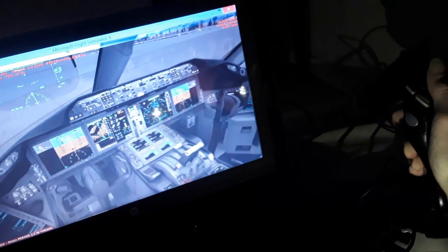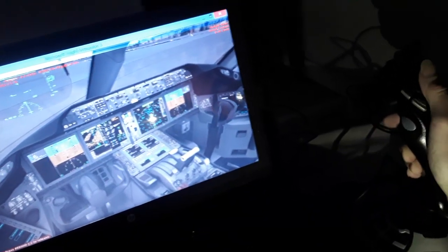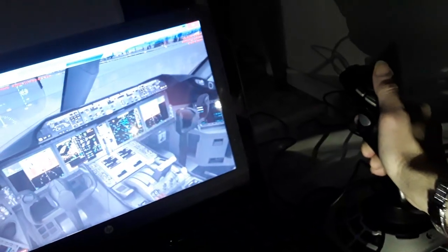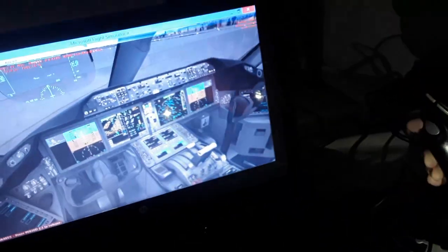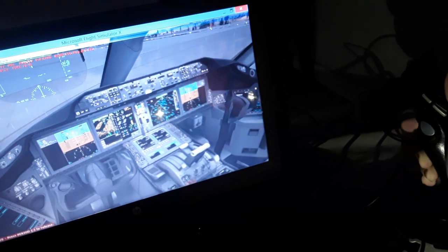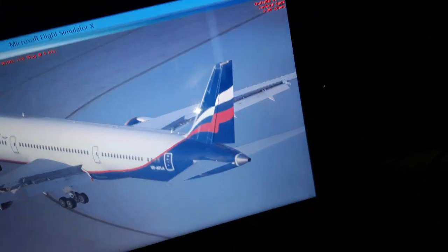So they're interconnected until some airspeed in takeoff, until maybe like 70 knots. We have control of both. So the rudder is aerodynamically effective. You have the yawing axis like this, the rudder pedals.